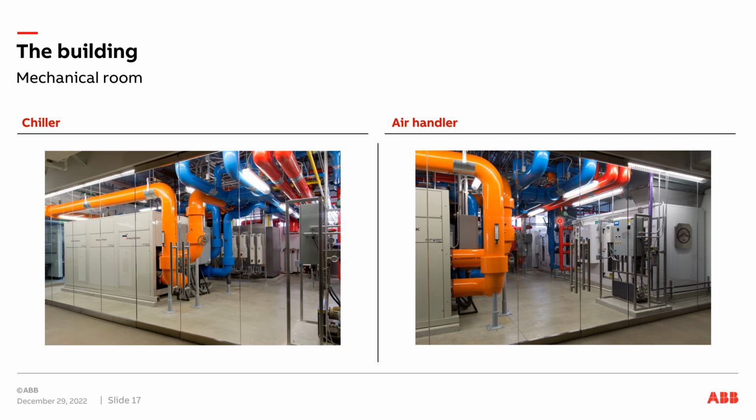I look over here, here's an air handler. Sometimes these will be up on the roof. We have one inside, the rest are on our roof, so this is the air handler. So remember early on I said that a typical air handler doesn't look like a big giant letter I with a tail on it. It's a big rectangle box. That's what this is. And then you either got air being ducted out either up or down, this one being on the main floor, so it gets ducted up and out, and then the return air is coming in back here.